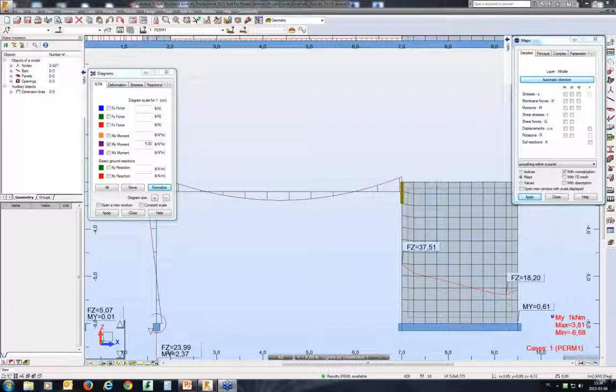But make sure that you haven't got any inaccuracy in the model, you haven't got any bar elements at the intersections, and check the generation of the kinematic constraints themselves.